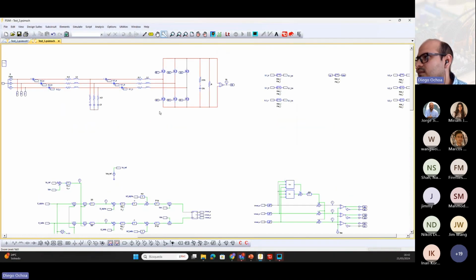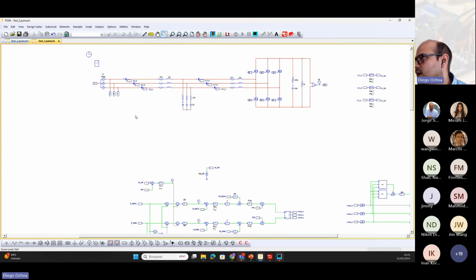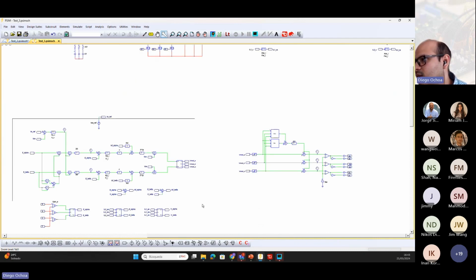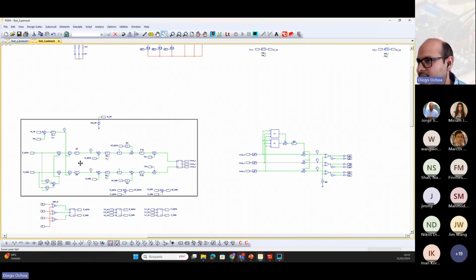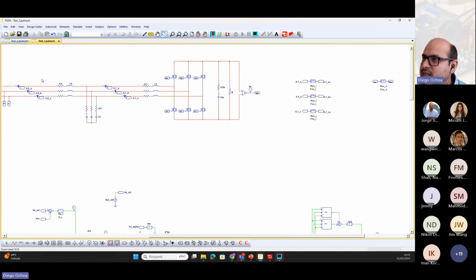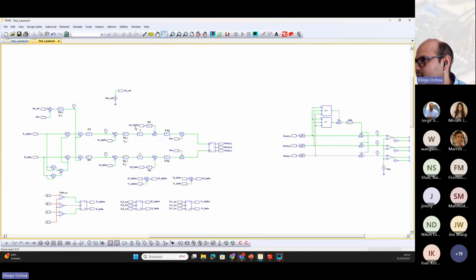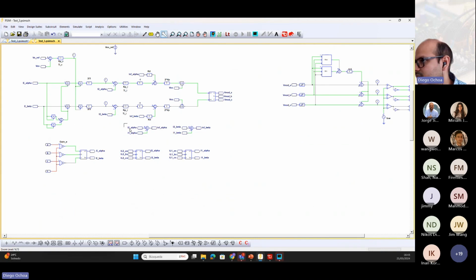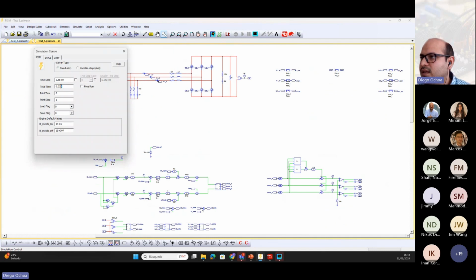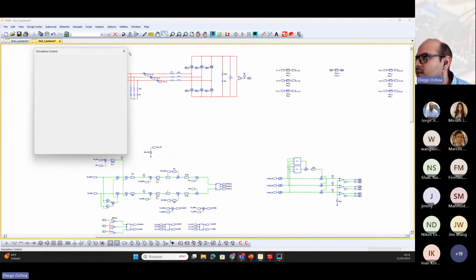Here you can see the power stage for the LCL filter, the sensor stage, and the control structure in alpha beta frame. Here you can see the active damping technique. In this case, we sense both inductor currents, and we estimate the capacitor current with this operation. So again, we can simulate this circuit, and you can see